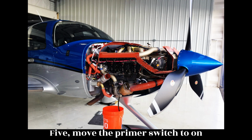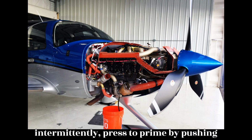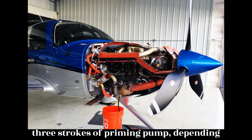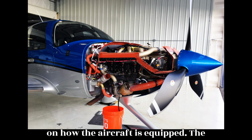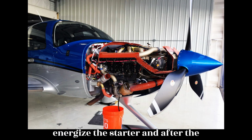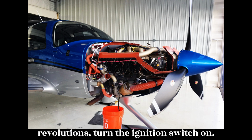5. Move the primer switch to on intermittently, press to prime by pushing in on the ignition switch during the starting cycle, or prime with 1 to 3 strokes of the priming pump, depending on how the aircraft is equipped. The colder the weather, the more priming is needed. 6. Energize the starter and after the propeller has made at least 2 complete revolutions, turn the ignition switch on.